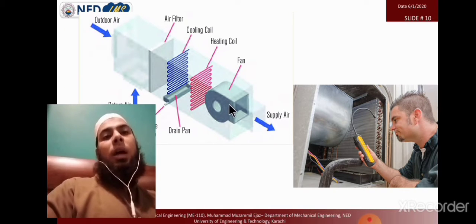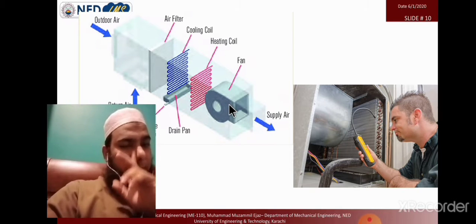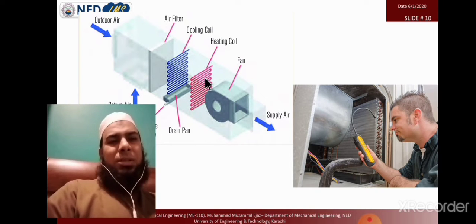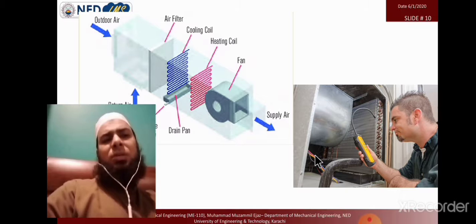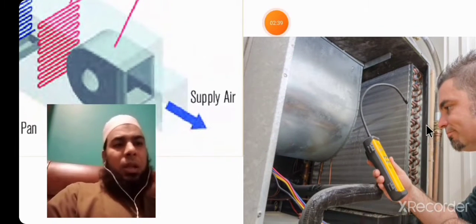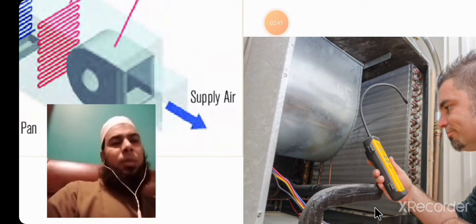to a certain point, where you need to have particular dehumidified air, just like in pharmaceutical companies. Okay, but normally a heating coil is not used in our system. When the air mixes with surrounding air, it gets heated to normal temperature, and thus the process goes on this way. This is basically the real picture of a cooling coil. The air passes out from this point, this is the blower, and water is collected in the bottom tray.